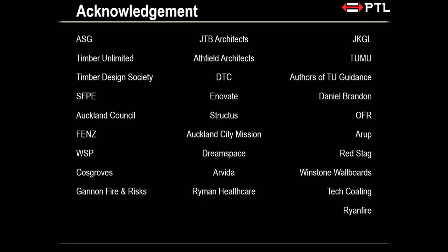There's other stuff, like a fire engineer. The first thing is sprinkler is our best friend. Sprinklers also have latitude to increase in performance. For a residential building, you will typically just do extra light hazard, the lowest sprinkler grade. But if you go 20-30 stories up in the air, maybe think about increasing it a little bit. It doesn't cost that much.